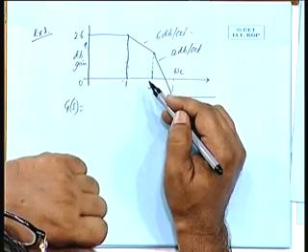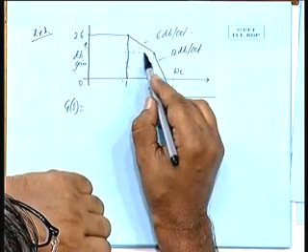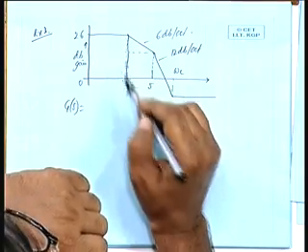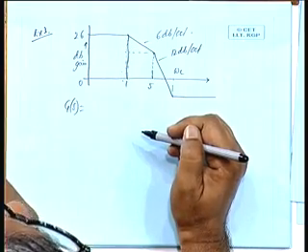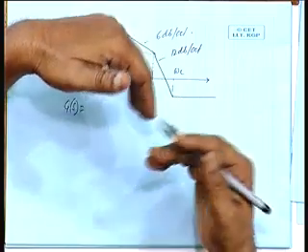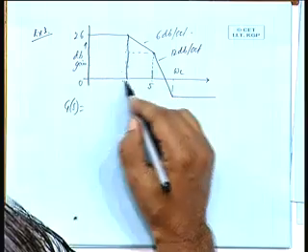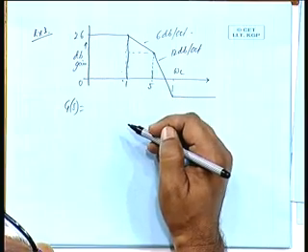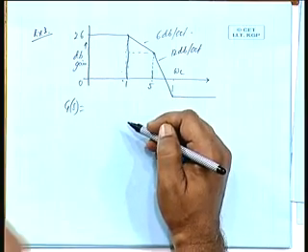6 dB per decade. So, how much is this fall? How much is this? 6 dB per octave. So, 1 to 2 is 6 dB, 2 to 4 another 6 dB. So, 12 dB, but then 4 to 5, so you take 20 log of 5, log of 5 is 0.7, 0.7 into 20, it is 5 times this frequency, 14 dB, is that all right?